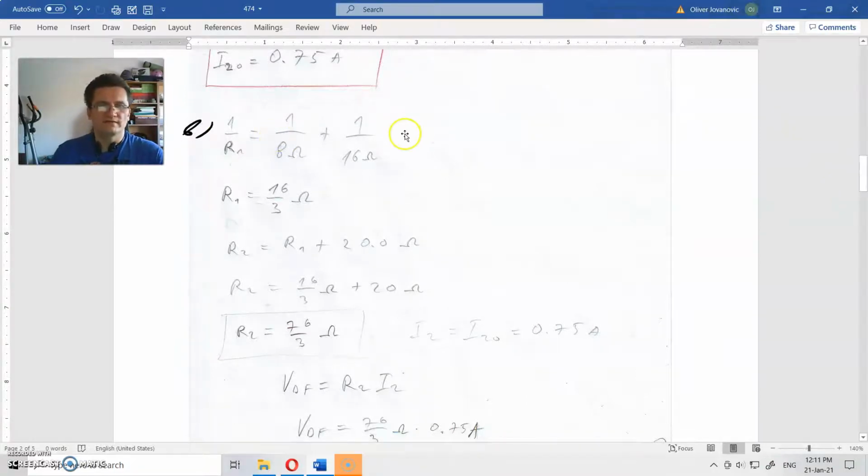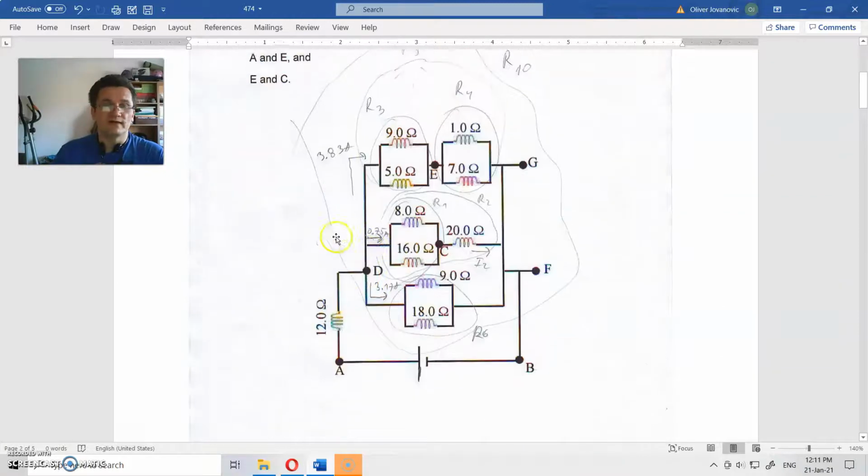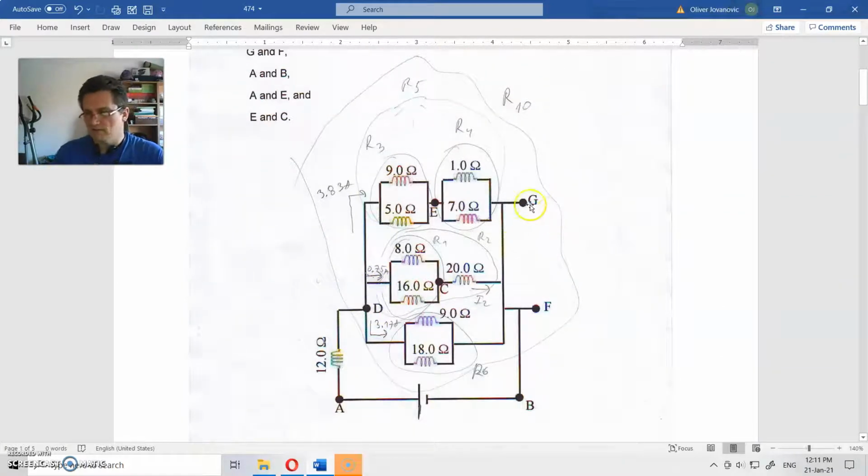First of all, we need to find some equivalent resistances in order to find all the currents and all voltages. So we will start with this because we have everything. So equivalent resistance for this part of the circuit here I noted as R1. And as you can see, these two things are in parallel connection. Then I noted this R2 to be equivalent resistance of everything here.